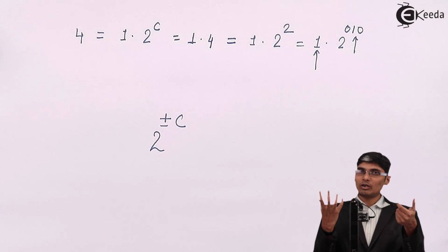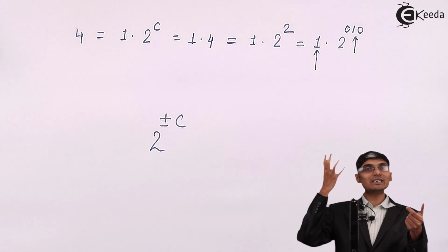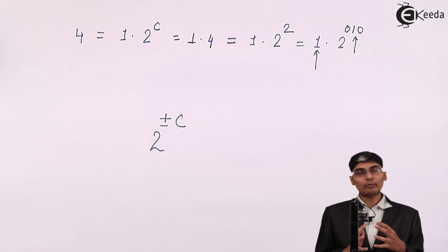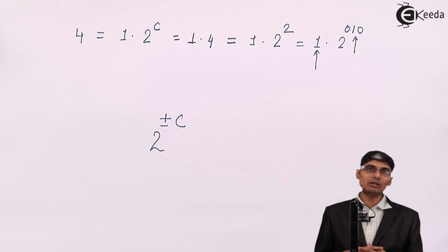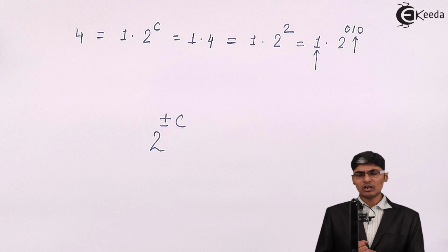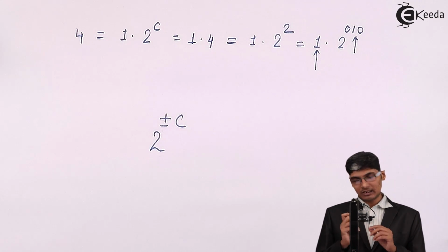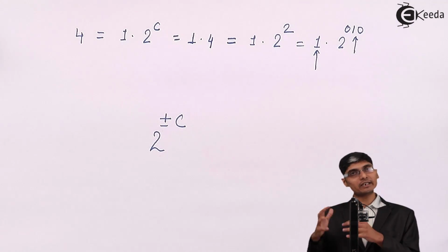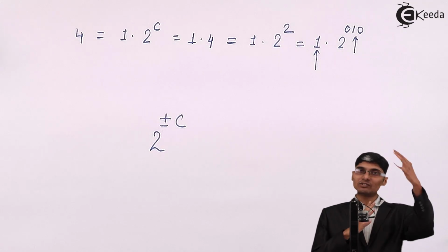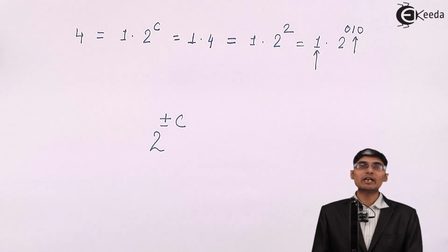I can keep the mantissa in the required bit length by changing the characteristic, the index of the two. In this way, floating point overcomes the problem of overflow in addition of fixed point numbers. But multiplication still has some problem, because you cannot move the characteristic arbitrarily. If the number of characteristic bits is fixed, then you have a certain limitation on the highest number you can represent.